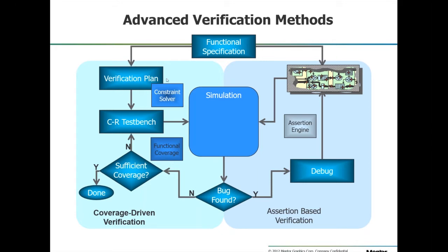So what I can do is design my test bench to generate packets of data and randomize whether or not I corrupt the data. I can change that data corruption rate, and I can keep cranking it up until I stop receiving packets correctly, and then I can say, well, what error rate was I at when that happened?